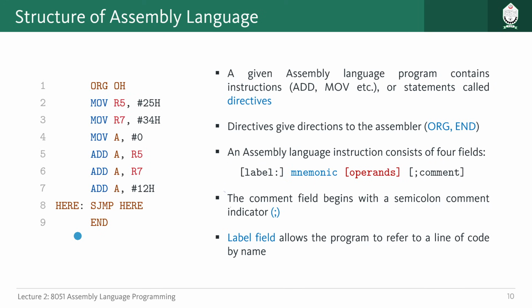Whenever we have assembly code, with a program called an assembler we convert that into machine language, and that machine language is understandable by our machine, the 8051 or any kind of computer, right? For that process, the assembler gets some directives, which are called assembler directives. These are not specifically instructions for the microcontroller. After conversion, these will not get converted into data and will not be saved into the ROM location. They are just instructions for the assembler so that it can understand how to properly convert the code.